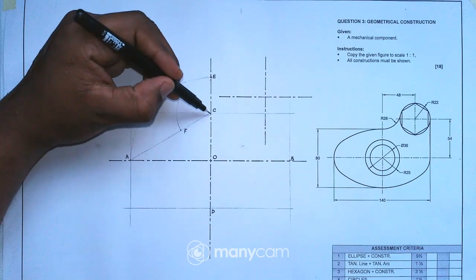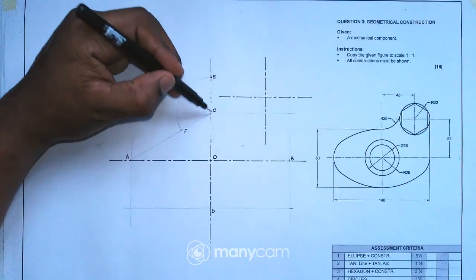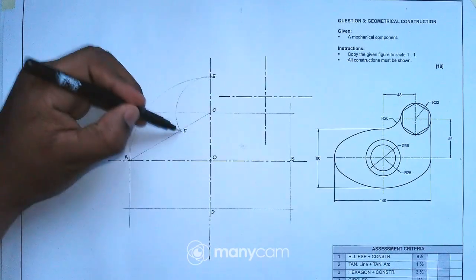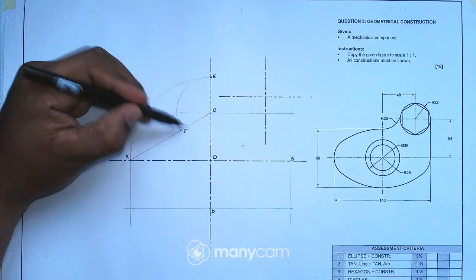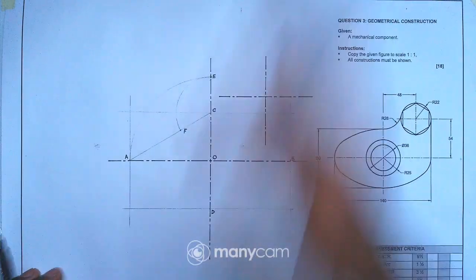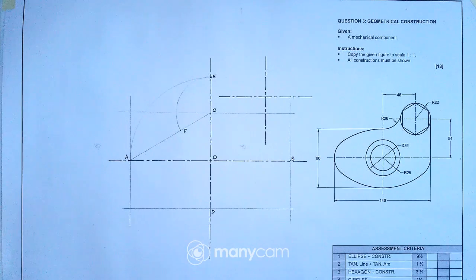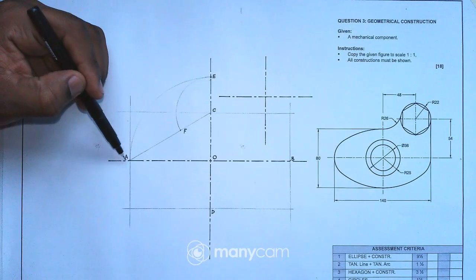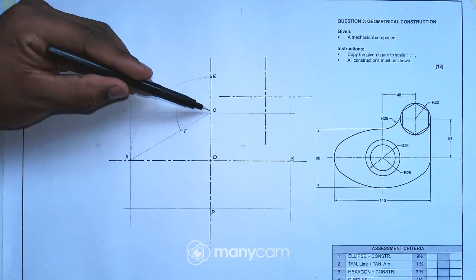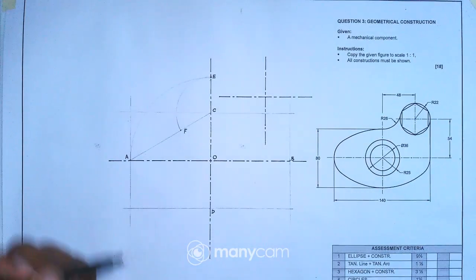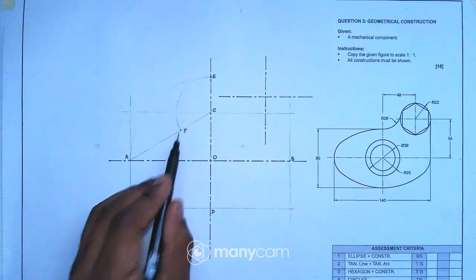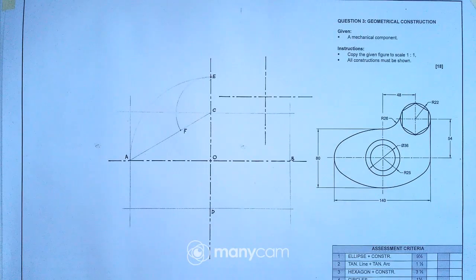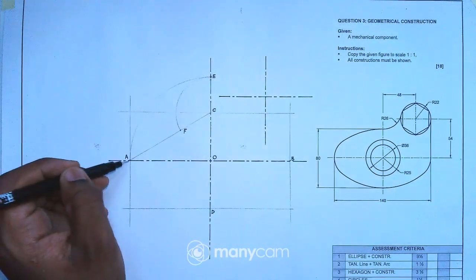But now you put your compass where? At point C, not at point O. So you put your compass at point C to point E, then you drop that point. And then you have F there. I hope we are together. So now, after finding this point, our focus now is on line AF, not AC, but AF. So now I'll have to bisect line AF. I guess by now everyone knows how to bisect a line, because we do bisecting of lines in term 1. So now we have to bisect this line AF.